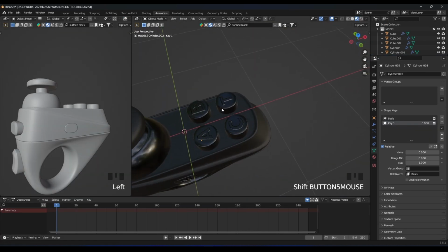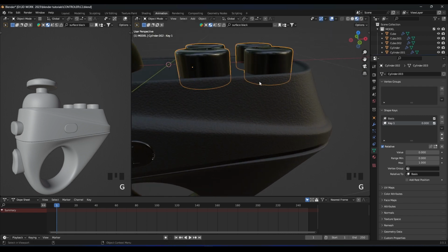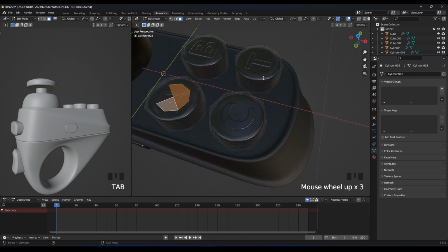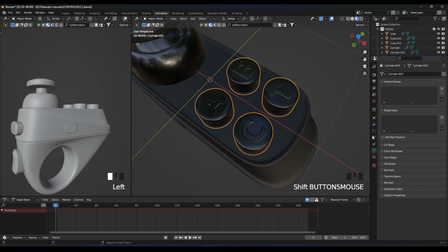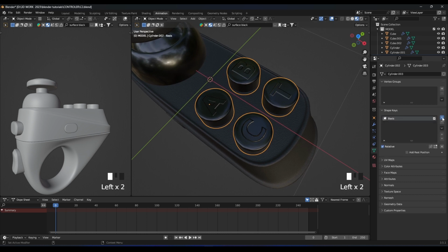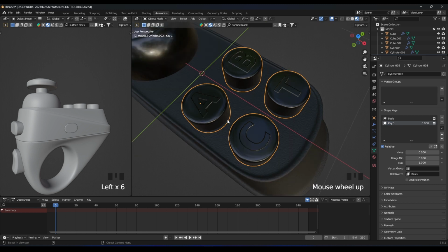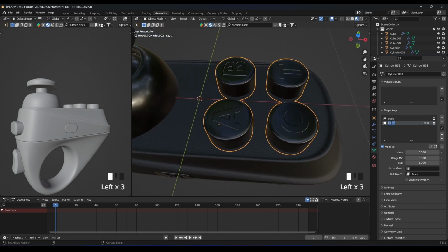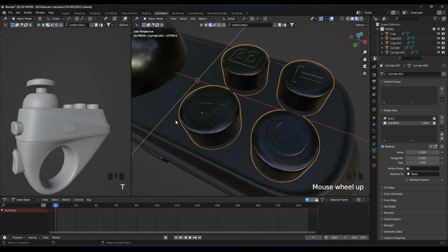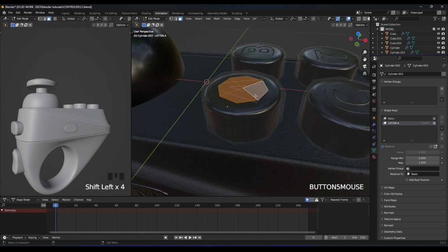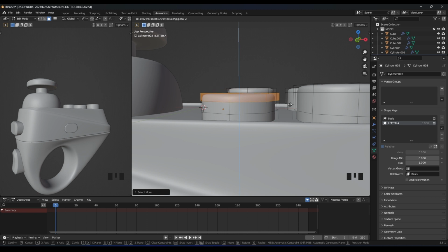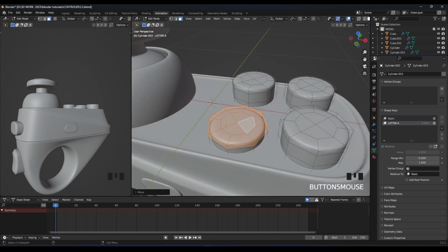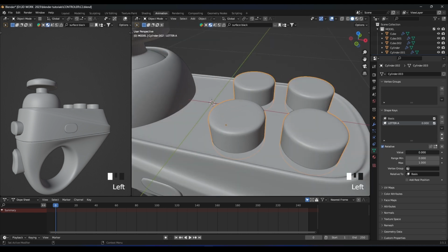What I want to do is just animate those buttons, so they will go up and down, but I need them to move individually. So every button moves on its own. We're gonna do this by using shape keys. So let's go here, add a shape key, and add another shape key. If we're gonna animate the letter A, we need to name this letter A, or name it A directly or whatever. Let's select these faces like this, press G and move it in the Z axis until it almost hits the second edge. Okay, now if we slide this value, see our button now moving.